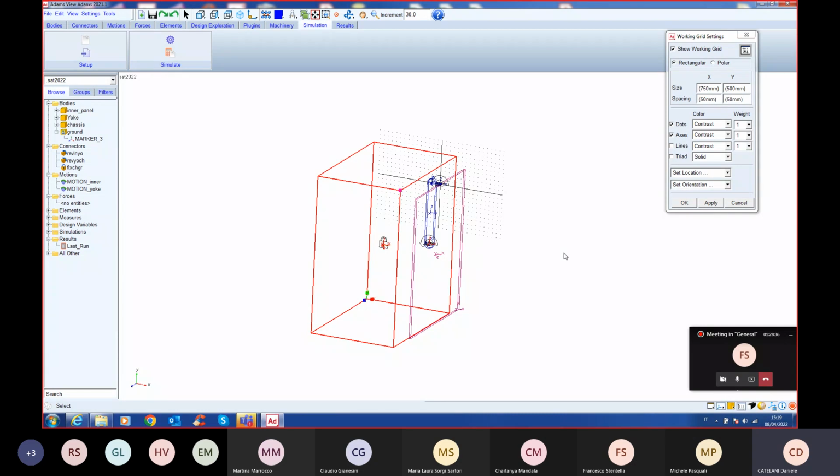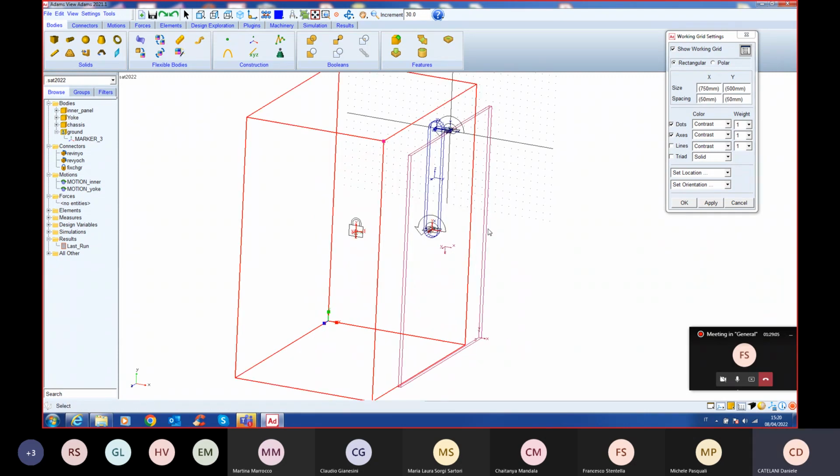The last thing to do is the external solar panel. We can repeat the same process as before, creating bodies, etc., etc. Or, due to the fact that the external solar panel is identical to the internal solar panel, we can go to the part inner panel and select copy.